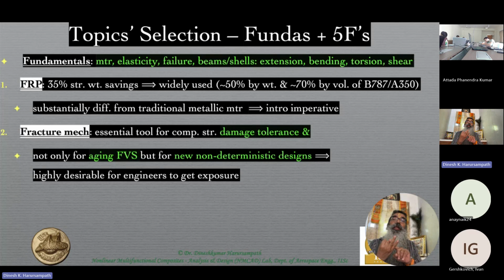So there is an uncertainty about the material properties, the uncertainty about the geometry in terms of the size, different locations and different shapes, and also in terms of the loads. Someone mentioned the differences in aerodynamic loads. Those loads, in the presence of winds or gusts, can be quite different, flying in different seasons, at different altitudes, at different locations.